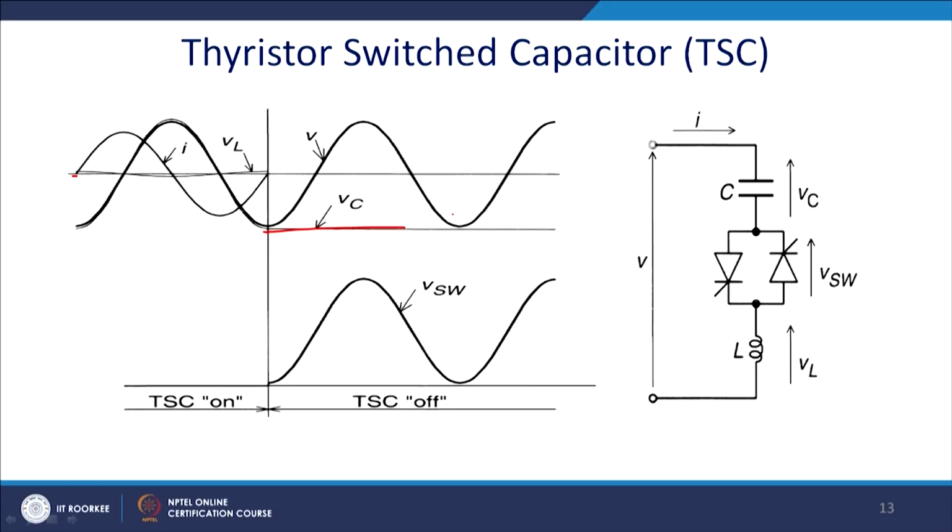The capacitor will maintain this voltage, and thus the switch will be subjected to this oscillation and will have a stress of the TCSC equal to V, if the value of n is, quite logically, very high. So, n square minus 1 is almost equal to n.